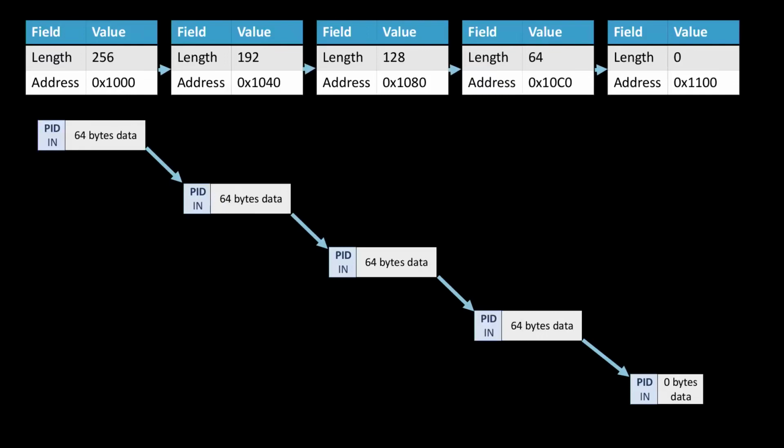It's going to send out a single packet of length 64, because it's the most you can fit in a single packet on this particular bus. It's going to decrement the length and increment the address. This looks a lot like the example we provided in the beginning. It's going to keep doing that until it gets to the point where the length field reaches 0. And USB is almost a null-terminated kind of protocol in that when it finishes a transfer, it indicates that by sending a packet that is shorter than the maximum length. So in this case, it sent all maximum length packets until it was done, so it has to send a 0 length packet in order to indicate that it is indeed complete.